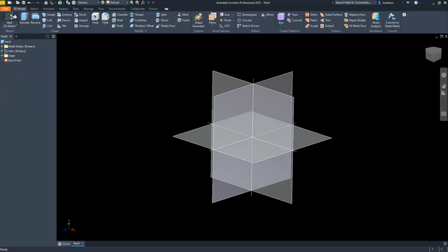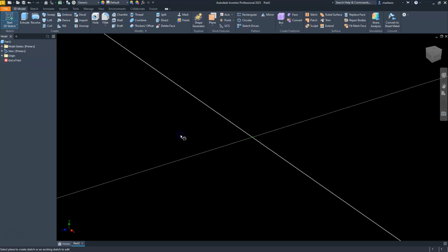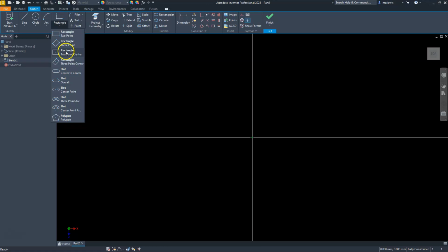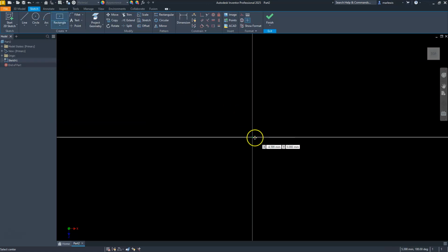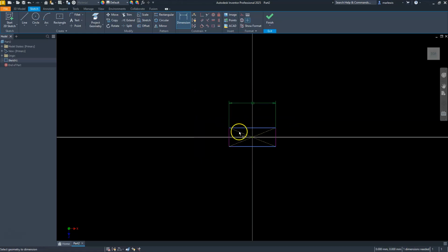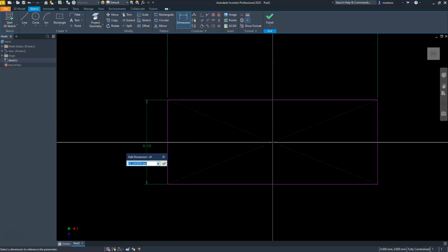All right, so we'll start off by creating the sketch here, and I'm going to start this one on the XZ plane. Once again, it's just kind of my little OCD. I like to have this top facing the right direction, and I just flip that with the little move handle there. I'm going to go to a rectangle, and this time we will use a 2-point center rectangle. So I'll select the center first, which is here, and then I'll pull out and give a preview of my rectangle. Let's put some basic dimensions that we need on this. The overall distance here should be set to 80. And then we're going to have another dimension here, and this overall dimension should be set to 50.